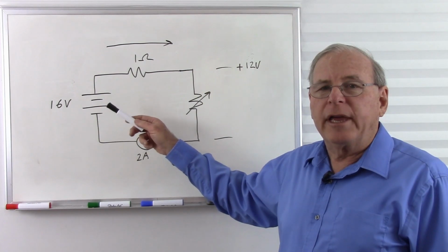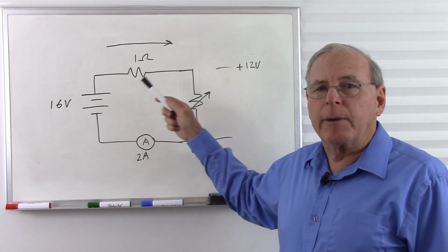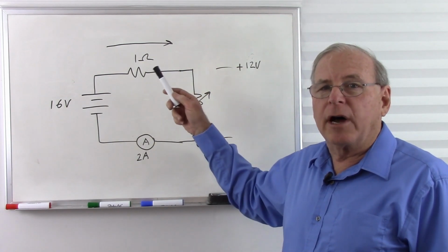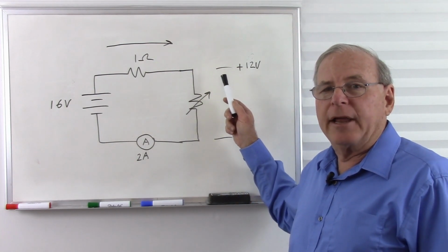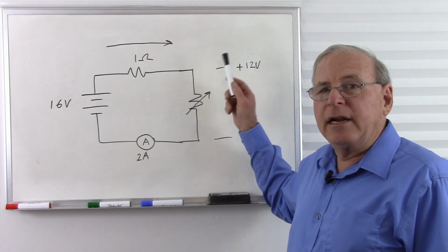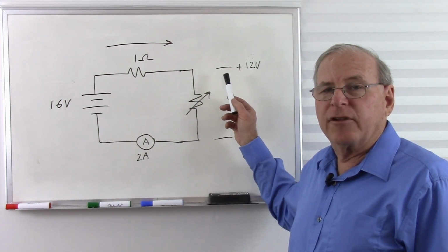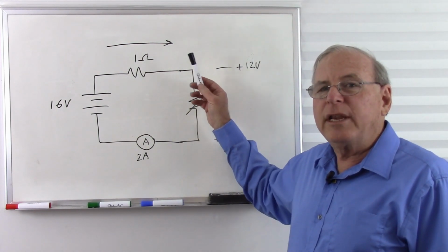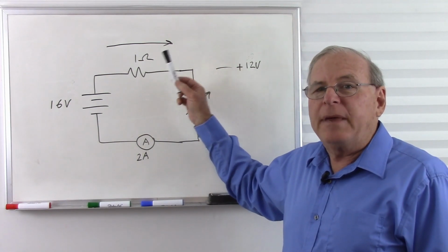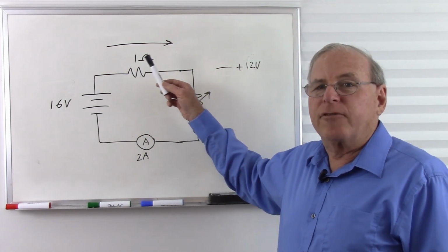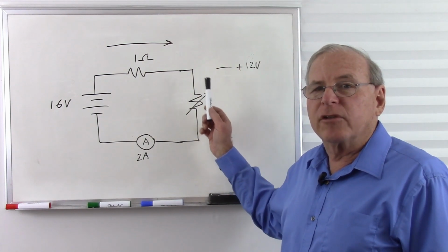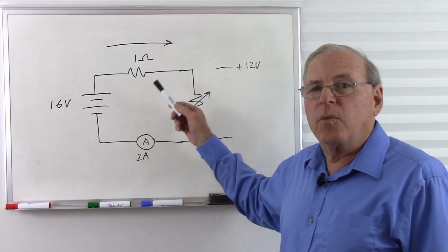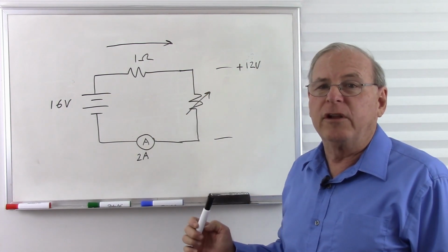So it's conceivable that if the output impedance of this transformer, represented by this resistor, is high enough, and I put a 4 amp load on here, my output voltage might not be high enough to operate the circuit. Now we needed at least 12.5 volts on the collector of the transistor, and we expected to lose about 1.5 volts across the rectifier, so we need about 14 volts peak off the transformer when that transformer is delivering 4 amps of current. So let's test that transformer and see if we can get at least 4 amps out of it when our peak voltage drops down to 14 volts.